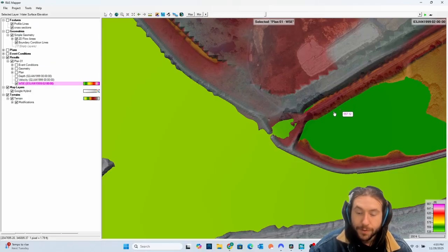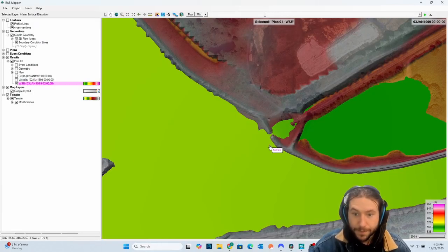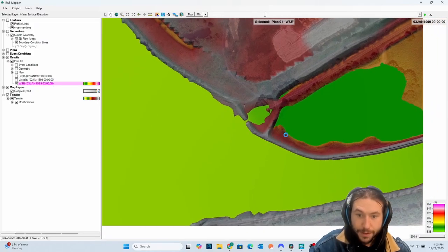But they leave the railroad at its current elevation because it would be really expensive to raise the railroad up to come up and over the levee. So they leave it at its elevation. They build the levee all the way up next to it, and then they'll put in a temporary blocker there during floods. So that way they can keep trains rolling through on the existing railway, but still have flood protection.